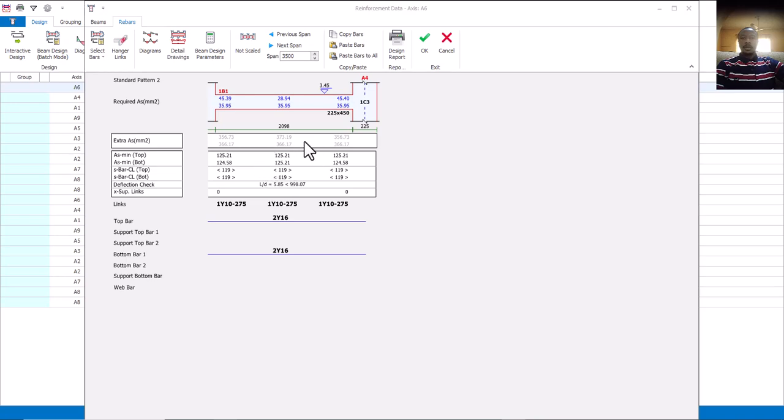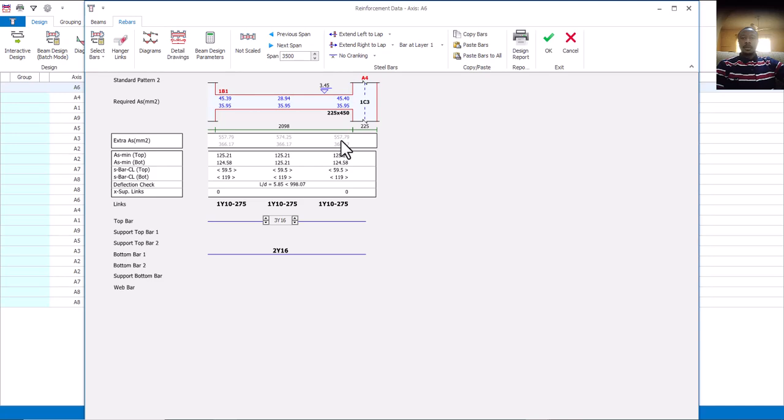That is fine. Now, the values up here, the reinforcement responsible for them is this one. This part, 2y16 up, is responsible for the values up here. If you take note, if I increase it now, can you see that the values have changed to 574 point something and 555 point something. So if I reduce it back, can you see now 370 something, this one 350 something. So it is this reinforcement that's responsible for the values up, and the values down are controlled by the reinforcement around this place. That is all about this place.